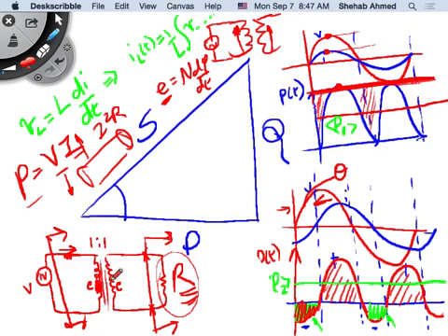Right, so this magnetic field that's linking the two turns is set up using the reactive power coming in. It's current that is not in phase with the resistive current. You were drawing magnetizing current into the transformer at 90 degrees with respect to the resistive, the core loss component. Correct. So it's exactly like a voltage source across an inductance. If you have a voltage source across an inductance, the current will lag the voltage, right? By how many degrees?